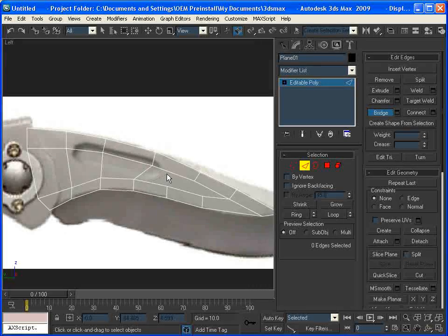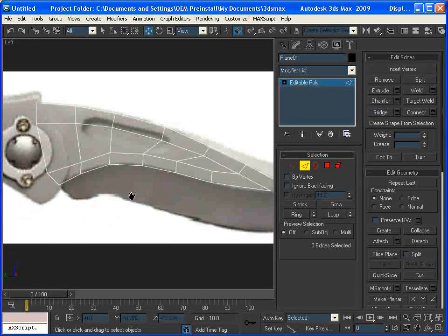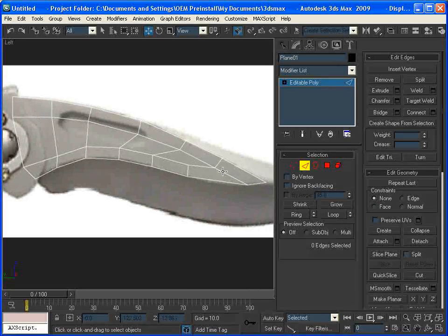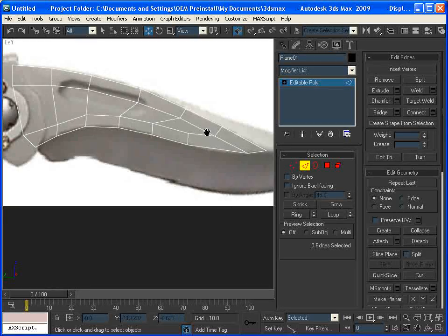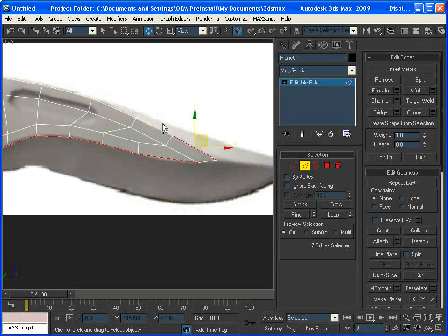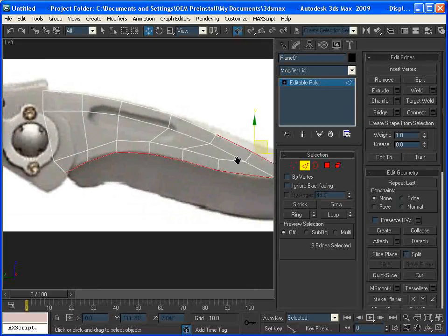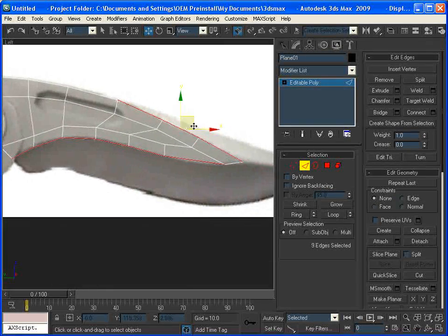For example, I'm just creating the side of the knife here. This area is totally flat, and yet I just made it with like two loops here and bridged in between. And if this was the low poly model, that would be a lot of wasted triangles. You wouldn't need any of those to actually change the form of anything, so they would just be sitting there being pretty, doing nothing. But with high poly modeling, it's actually going to be useful to have those there because I can run connections down them later and tighten up some edges, which we'll get to in a few minutes.